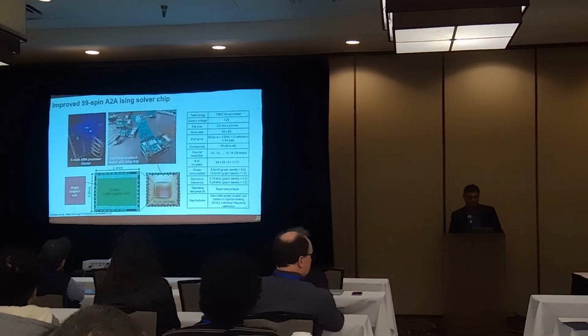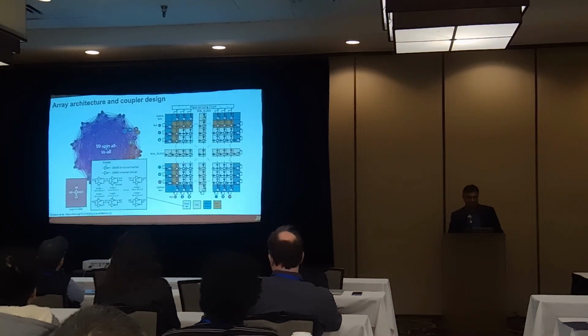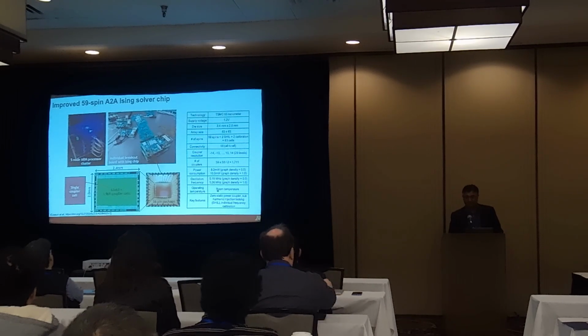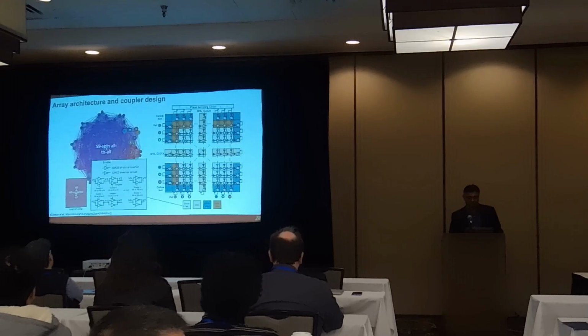To avoid this, we came up with a scheme that used gated transmission tri-state structures that eliminated the static power. And this is a 59-spin structure, and again it operates at room temperature, oscillates at about 5 megahertz, etc. No static power, and the total power is 10 milliwatts as shown over here for the greatest amount of coupling.